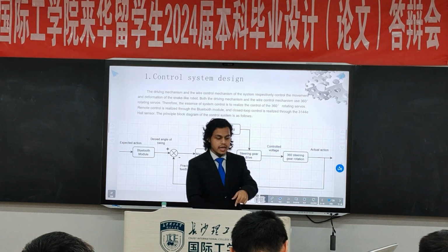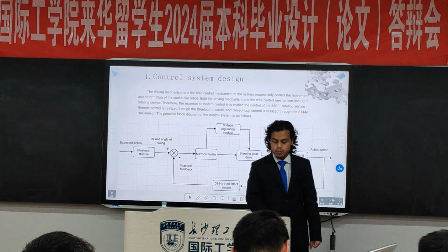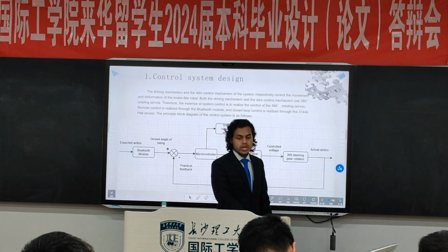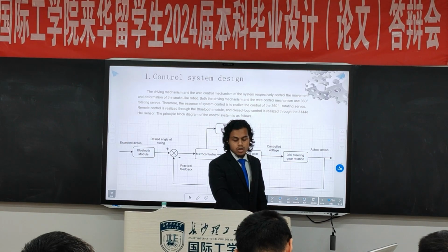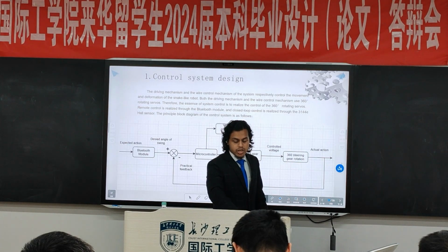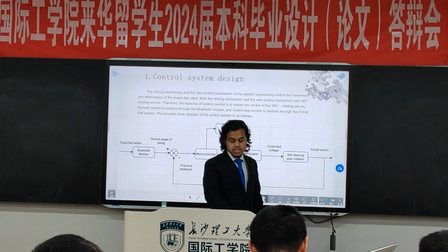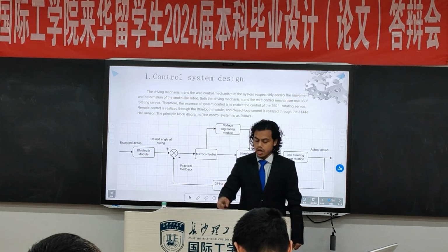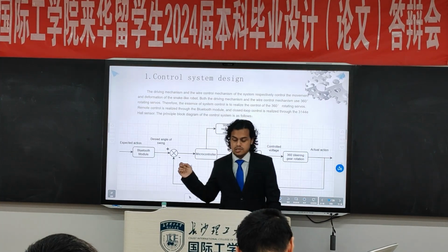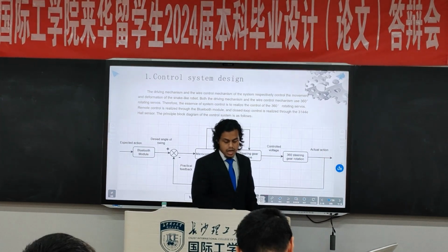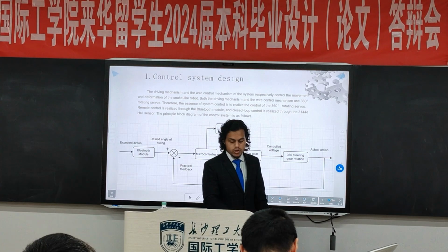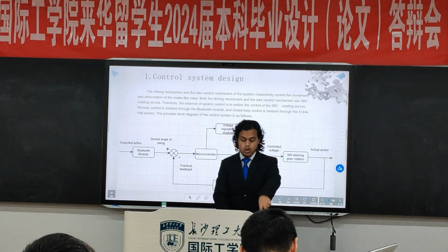So the control system that I can show you: the input is a Bluetooth module, and we can see the microcontroller. We have used an Arduino Uno Nano, a voltage regulating module, a steering gear drive, and a 360 steering gear rotation. I have already told you it was the gear stiff motor I have used, and the Hall effect sensor, which is the 3144E. This is the control system.